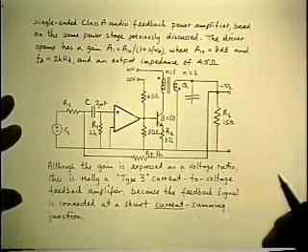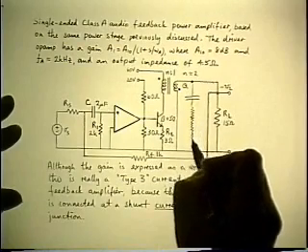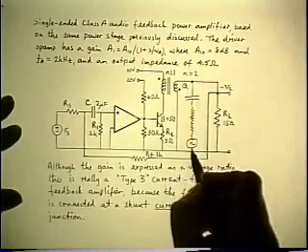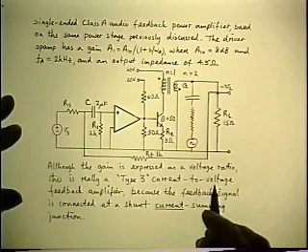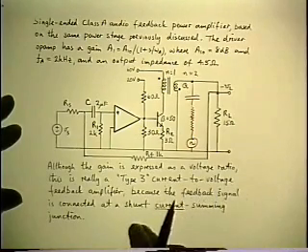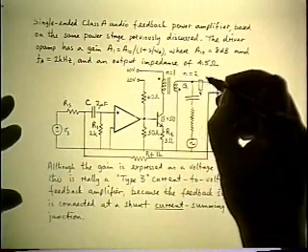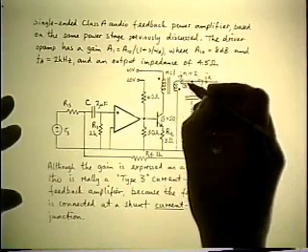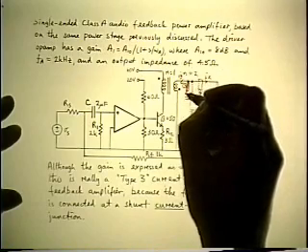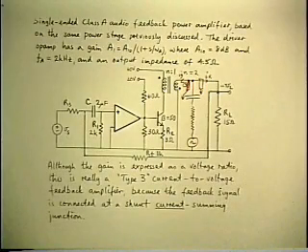Well, most of our signal sources are actually voltage sources, and so all you have to do is put a huge resistance in there and drive it from your voltage source. Then the measurement that you're going to use is a ratio of IY to IX. So you use two clip-on AC current probes, IX and IY, another one over here. And you use them in the normal manner as current measuring devices.